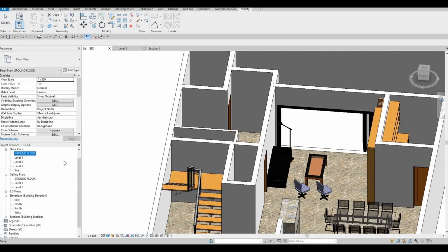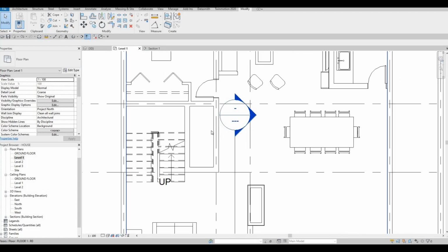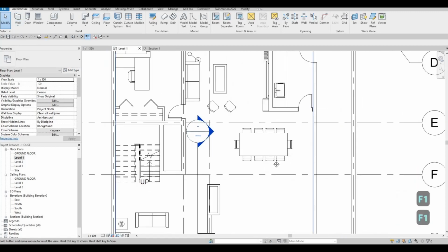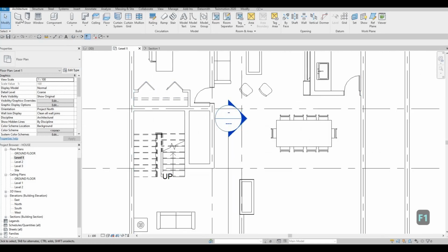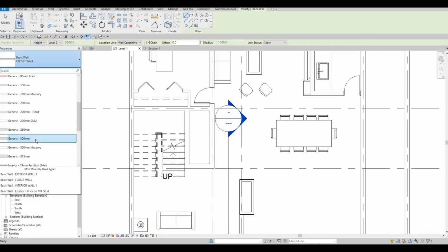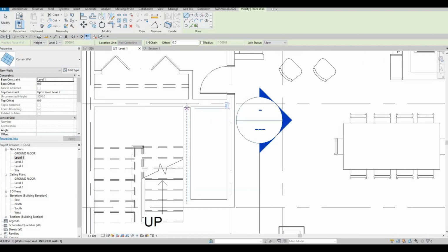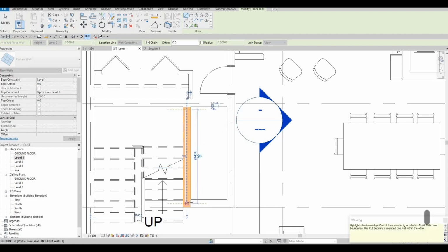And then here, this will be glass, and the good thing about that is it will be glass all the way to the top, because that's our mini garden right there. So let me do that. So we need to go to wall, and then we need to choose curtain wall, and then let's just add curtain walls right about here, and then here, and then here.